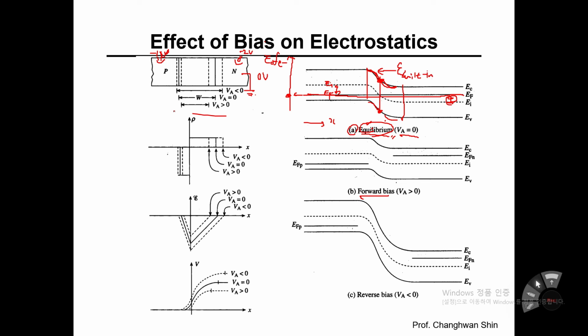So always compare against the voltage applied onto the N side how much voltage has been applied onto the P side. You should always take into account how much voltage difference has been applied between P and N. So the sentence that positive voltage always indicates a forward bias is definitely 100% wrong.